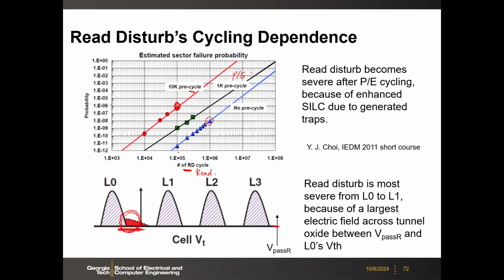Of course, the error rate is low, but you have a large capacity, right? For example, an error rate of 1e minus 6 means one error out of 1 million cells, 1 megabit. But your flash easily has gigabits. So you still have quite a lot of errors due to this. That means you have to use error correction and other mechanisms to protect the data.